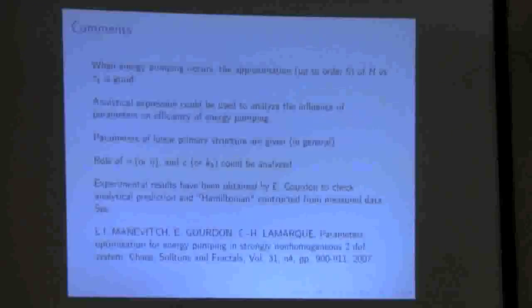And if I consider that parameters of the linear primary structure are given, because sometimes the primary structure is an existing one, I can study the influence of eta or C parameter, and you see that these two parameters could be related to the coefficient of the cubic term and the damping of the coupling. Okay.